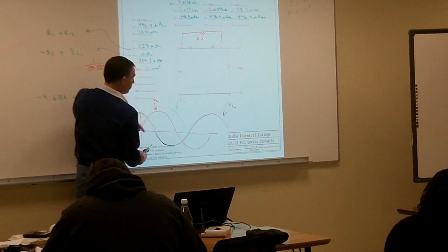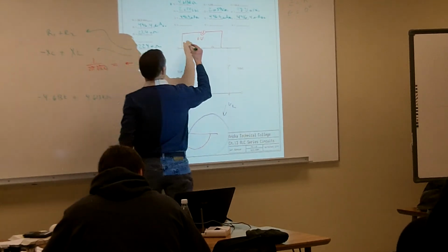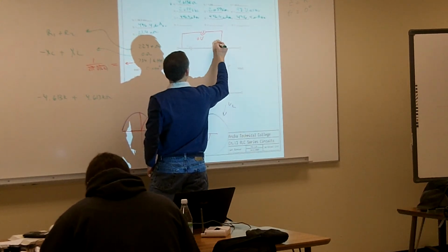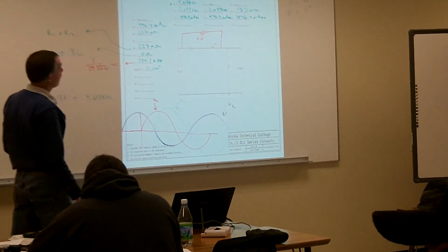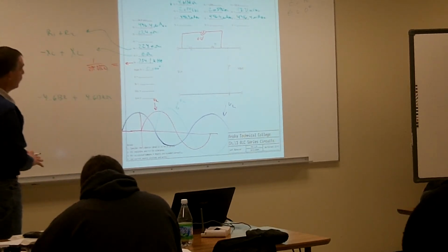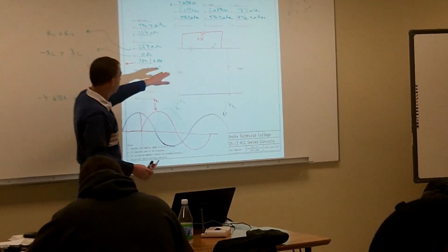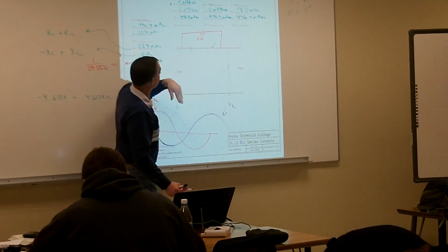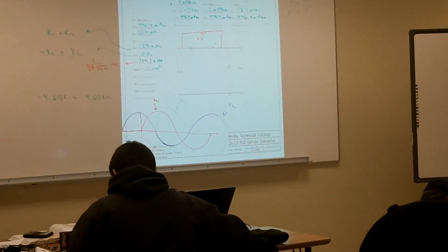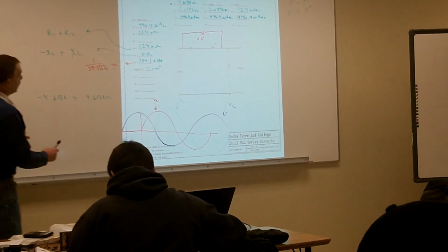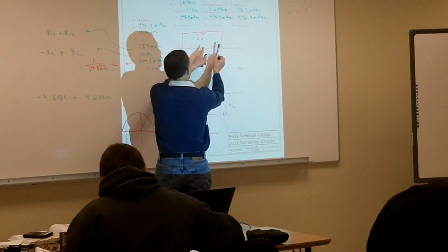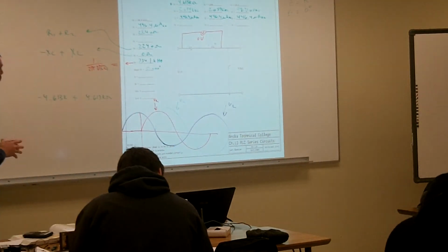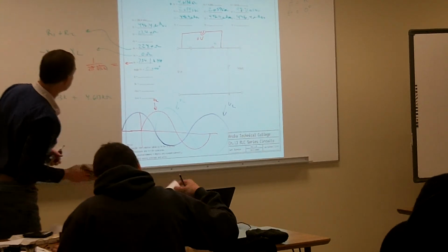They're going to oppose each other. Because at one half of the cycle this one is going to be positive, negative, and this one's going to be negative, positive. So those two are always opposing each other. But they take all the energy that the inductor produces, the capacitor stores it, then the capacitor discharges and puts it back into the inductor, and the inductor opposes that change in current. So that's where we get 0 volts going across it. If I measure them separately, I will measure that 2.059 separately, but going across both of them, they cancel each other out because of their polarities.